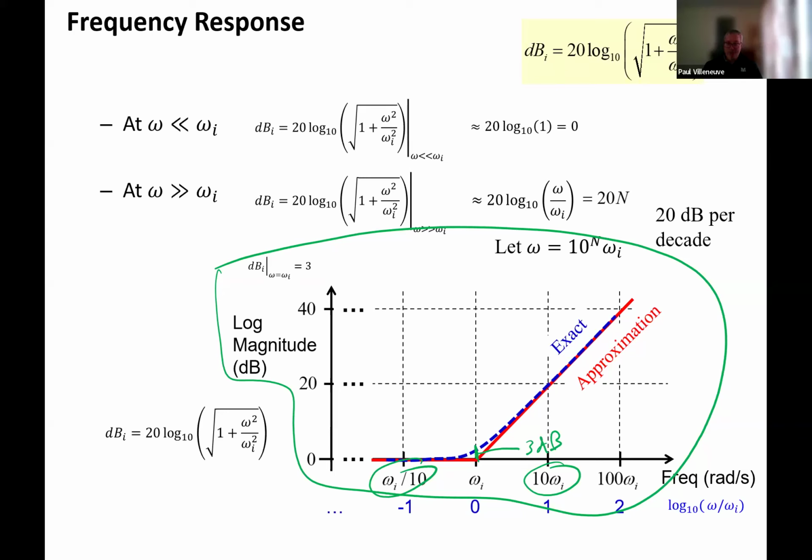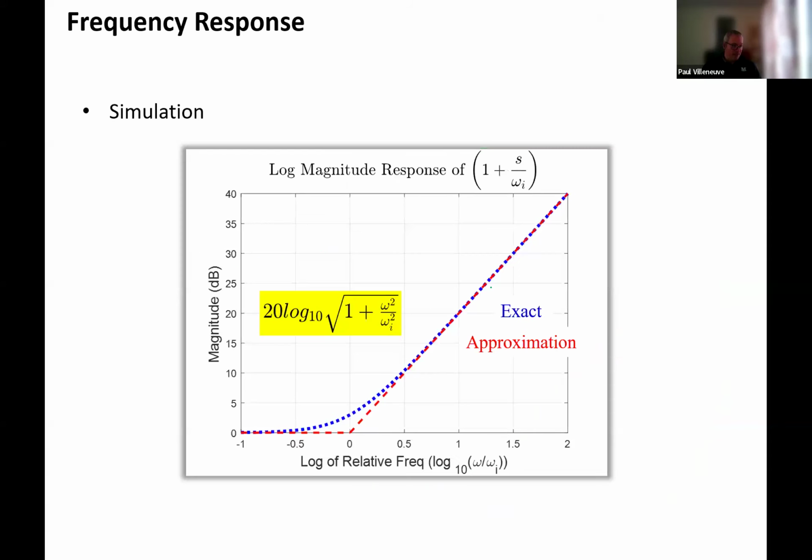Yeah, but this is how you actually do the math behind it. We do everything in semi-log, and you can see this is semi-log paper because look, this is 1/10, and the spacing between 1/10 and 1 is exactly the same as the spacing between 1 and 10. So this is on a logarithmic axis. But over here, the difference between 40 and 20 is exactly the same as between 20 and 0. So that's why we would call this semi-logarithmic paper. And that's how you do the calculations for doing attenuation or doing magnitude plots. Okay, so here's a 3 dB, et cetera, et cetera.